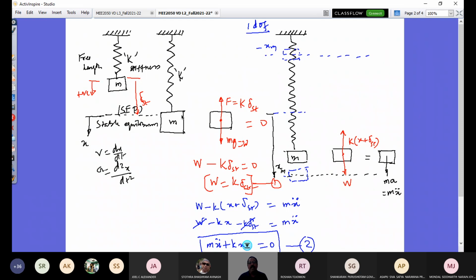And then further from static equilibrium position, then you give initial condition for this. So the initial condition of two kinds. One is from this static equilibrium position, you can give an initial velocity. That means just to give an impulse from there. The velocity, because of that, the mass would be going to its extreme position, and where the velocity is zero, that's called point of reversal. Then it will be reciprocating about its stable equilibrium position. That is one way you can execute this simple harmonic motion.